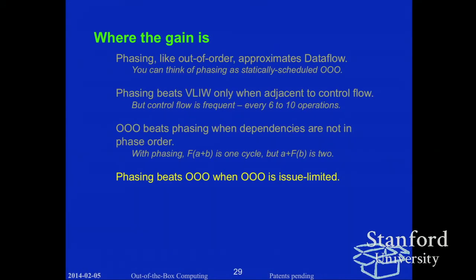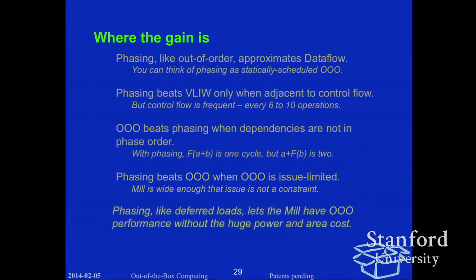And furthermore, out-of-order hardware is extraordinarily complex, extraordinarily large, and extraordinarily power hungry, and you've hit diminishing returns, and even 8 is pushing it. The Mill does not have these constraints. It is extremely power stingy, and it puts its area into functional units, which are tiny. So the Mill does not have constraints that make it issue limited, or at least family members don't.